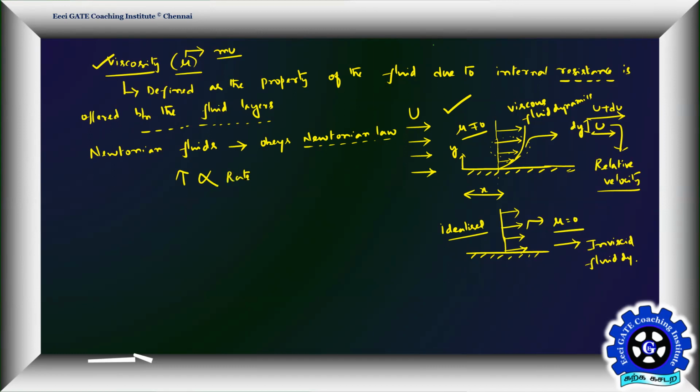Here you should not say shear strain in fluid mechanics. It is a rate of shear strain. If you see for a particular fluid from experiments that shear stress is proportional to rate of shear strain, those kinds of fluids are called Newtonian fluids, and the law is called a Newtonian law. Are you guys clear? Understood? Everybody? Fluids which obey a Newtonian law, that is shear stress directly proportional to rate of shear strain, are called Newtonian fluids.